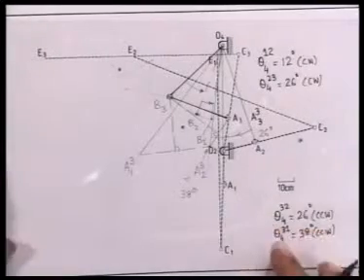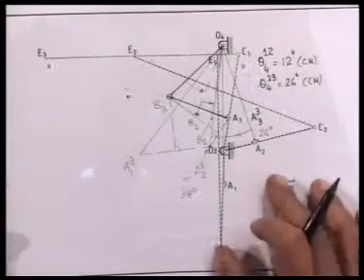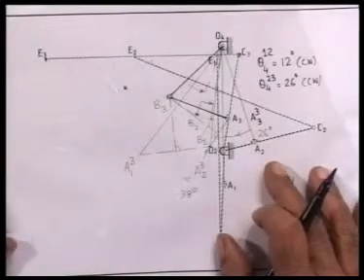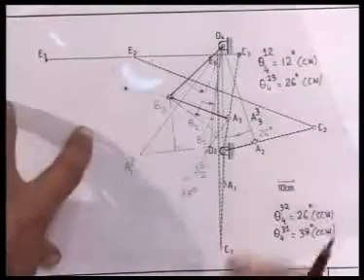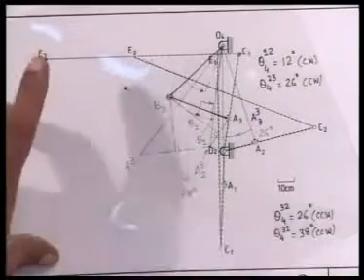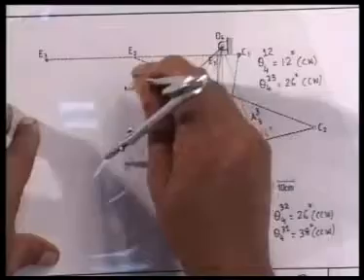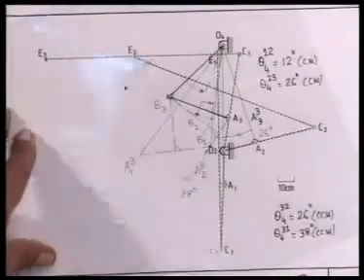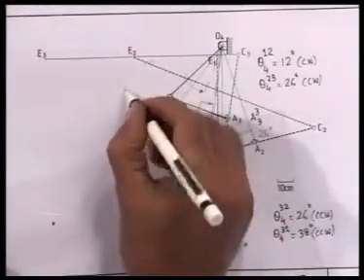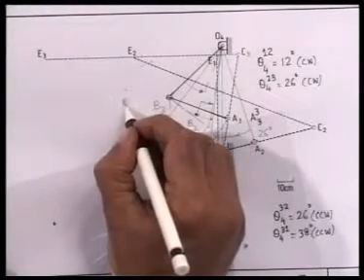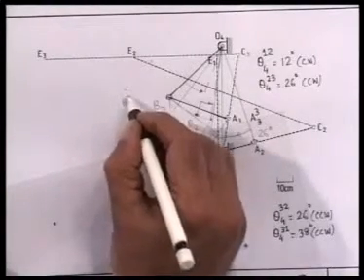If the door board is held fixed in its third configuration, then C2 is made to coincide with C3 and E2 is made to coincide with E3, and wherever B2 goes, this point I mark on my drawing sheet, which is B2 inverted on the third position.